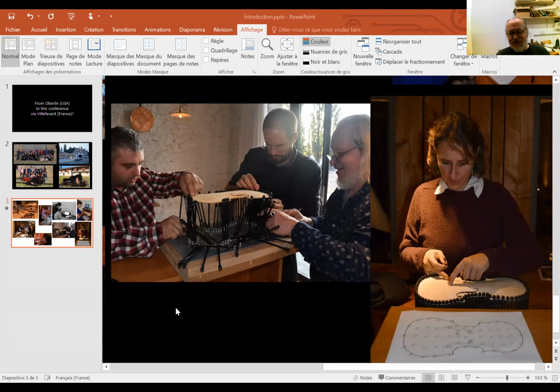But in fact, the assembled instrument has a very complicated set of boundary conditions, because in some ways it's partly like a pinned edge, it's partly like a free plate, and each plate contributes to the boundary conditions of the other, so there is strong coupling of the plates. But conceptually, it's quite simple. And when you look at the different mode shapes that you get with the free plate and the pinned edge, it starts to shed light on why they behave in a particular way.